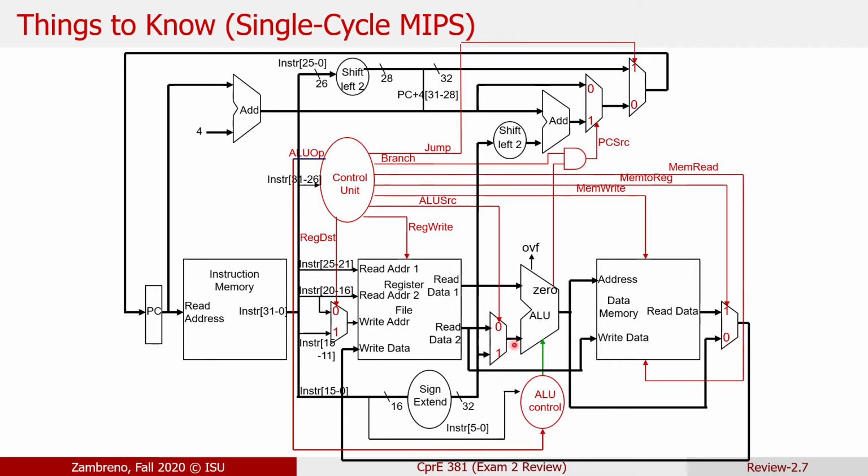And then for the load word instructions as well as for the store words, it's not the actual result of the add that we care about. It's the result of the add operation that corresponds to an address in memory, right? The load word and store word is using the ALU to calculate an address. It's a base register plus a constant offset. And then depending on if it's a load or a store, if it's a store instruction, we're done.